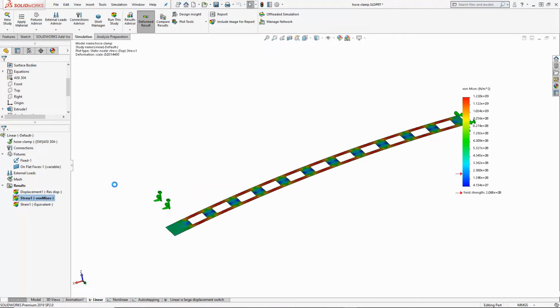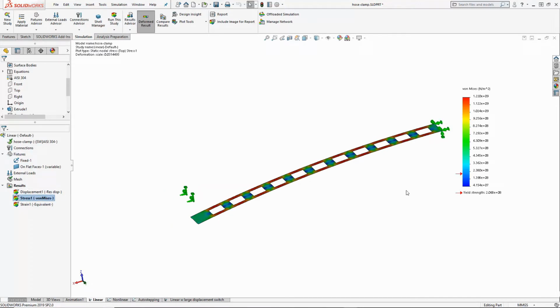So when I first switch to stress results, I think, well, that doesn't look like 360 degrees, but the deformation is pretty small. So maybe I should start with displacement results. One thing I see is that the stress here is way above the yield strength of the material. I can tell by the red arrow right away. I'm going to have a factor of safety below 1. The thing seems very broken. And that would happen if we continued along a linear curve and didn't account for any of that permanent deformation. So let's check out displacement.